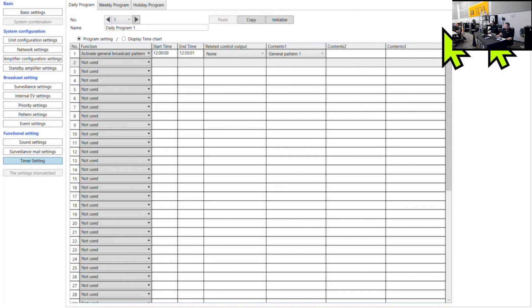For the time sync, I had a similar situation. In a scenario where you can't use an NTP server going to the internet, I know there's something known as a GPS NTP server. So you're relying on GPS, where you have a component that works somewhere outside in the field. It goes by the NTP, like a satellite, and you're able to get NTP server through that way, which is not the internet.